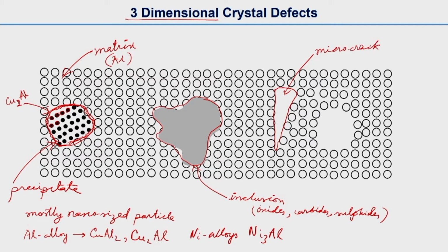These micro cracks generally do not grow very big, you know. In a material a good number of micro cracks can always exist, but material failure generally does not happen from an individual micro crack. And similarly, there are voids, mostly we call them micro voids. As you know, for ductile material the failure depends on these voids or micro voids.